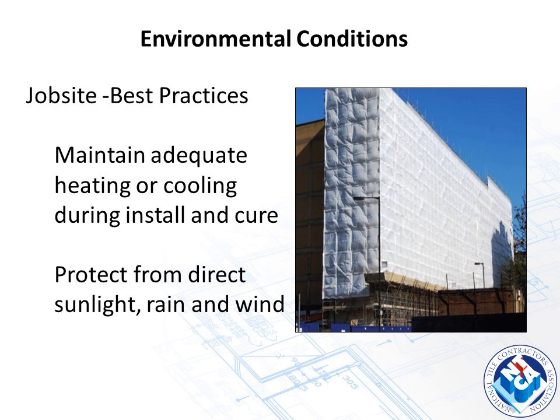Now, this is obviously a large commercial job and well protected. You might just have scaffolding running up to the parapet and a good visqueen over the back of it and tied off, etc., so that at least you're not getting the driving wind. But consider protecting the installation from direct sunlight, rain, wind, etc., not just during installation, but for a good minimum of 72 hours after installation while the materials start to cure.